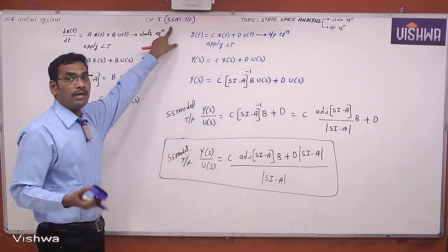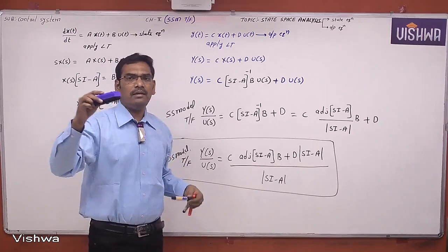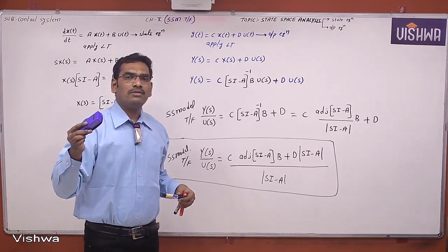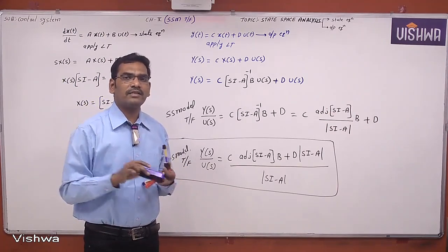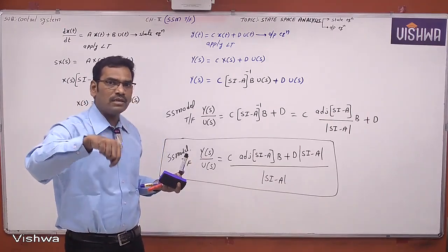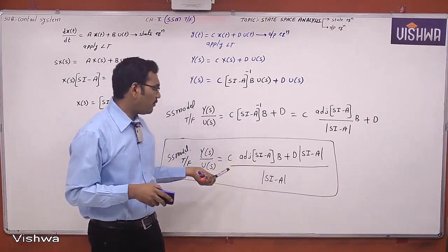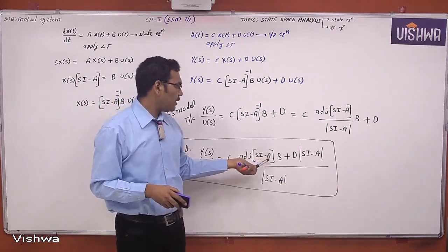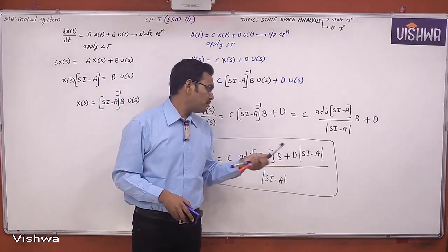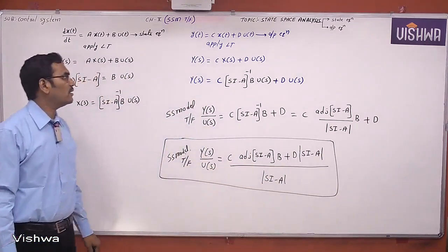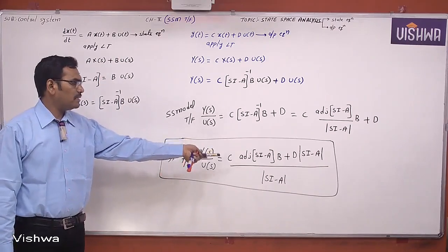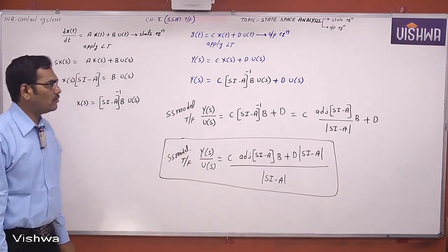This is one question that may be asked. Question number 1 is the state space model from the differential equation. From the differential equation you can get the state space model, the A, B and C matrices. From the A, B, C matrices, a linked answer question may be asked for the transfer function. If you want to solve for the transfer function, you require the C matrix, the A matrix and the B matrix; if you have a D matrix, you can take it, otherwise remove that part. So the determinant, the adjoint, and A, B, C are involved in finding the transfer function. Okay, note down this.